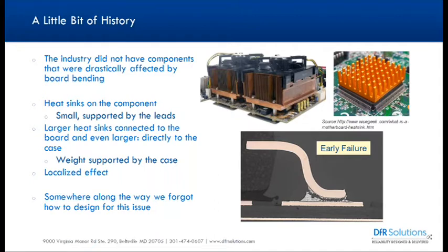I've been talking to people over the last couple of years, and they basically said, well, we used to make a heat sink for one component. Now we have more components that are dissipating heat. So we just made the heat sink bigger, but we still kept it glued down to those components. Or we only kept it with the 4 staking points for the aluminum heatsink. And they never thought about what happens to the aluminum versus the board because it's never been a problem.